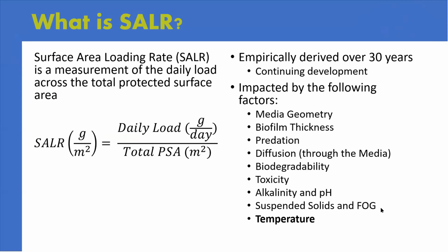So instead of thinking of it as, oh, I can just pick a surface area loading rate and therefore that will tell me how much media I need, instead, it should be looking at your system holistically and figuring out how much my system can actually handle.